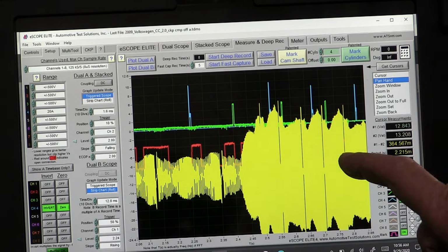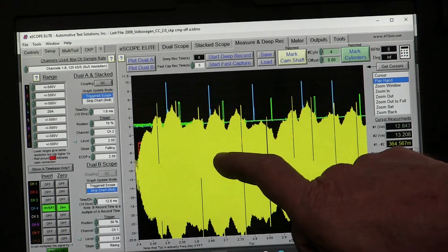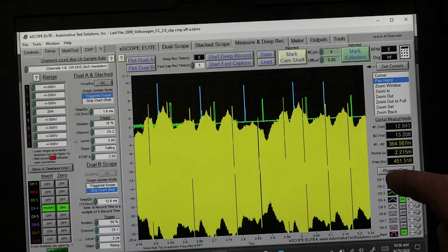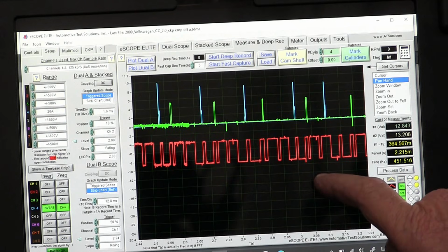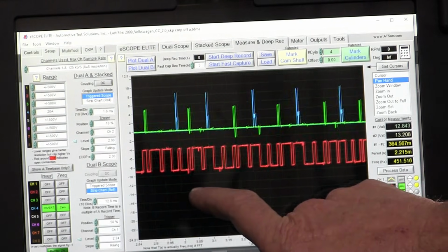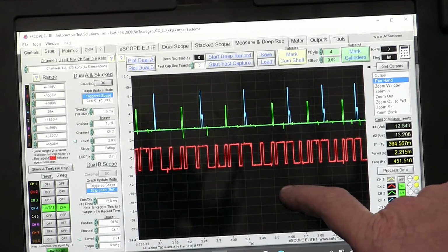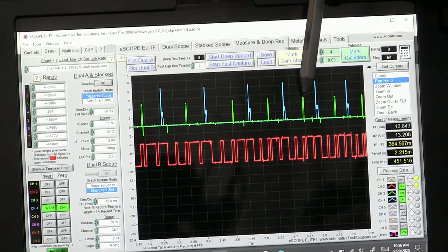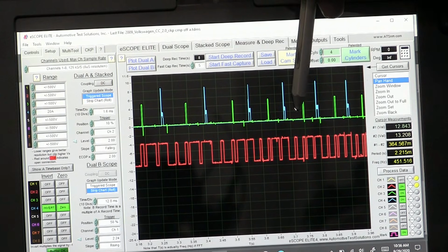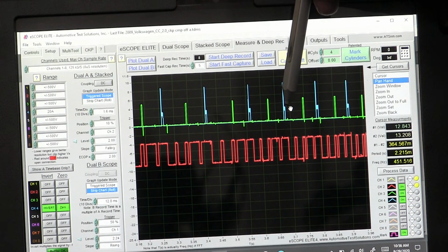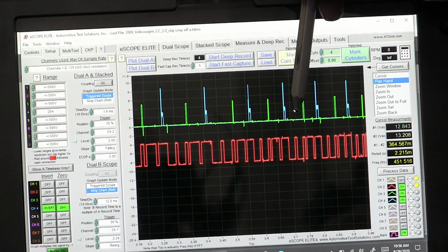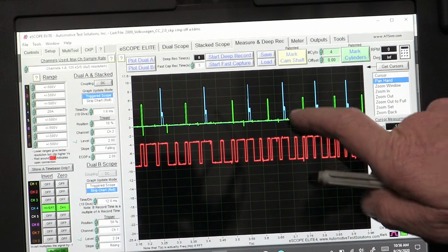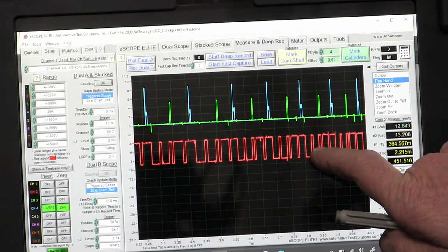The next thing is where these are firing. So let's go ahead and look at these across. I'm going to shut the crank off. We're going to come across and look at these. Now normally the injector fires when the intake opens, which is over here. This is in the exhaust plane and this is a GDI. I expect this to open 30 degrees after valve opening, which is closer to the tower. So this isn't happening in a time sequence.